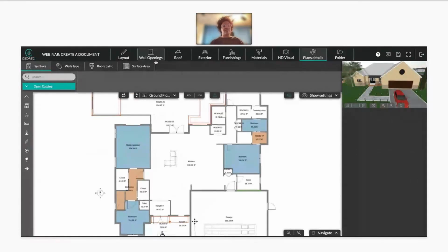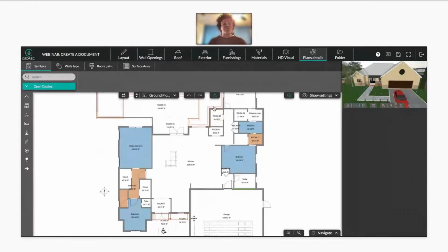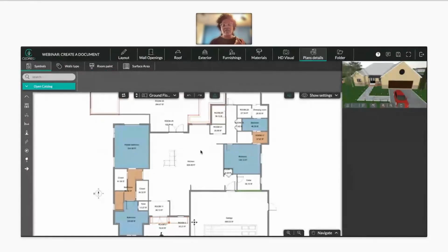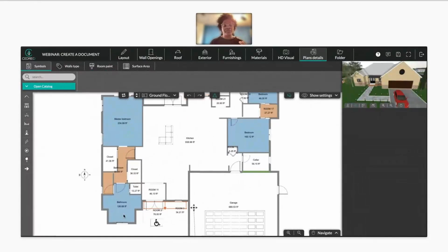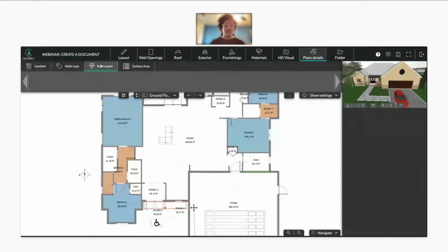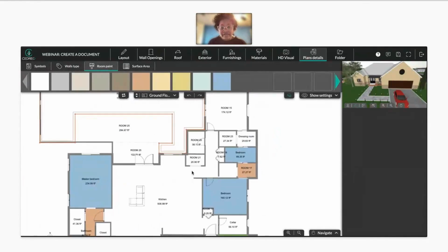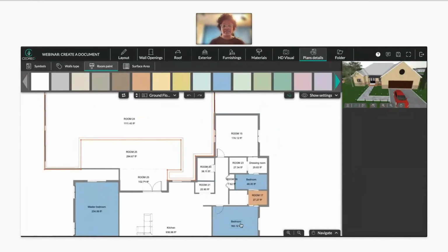All right. In your plan detail step, you can choose what these rooms are. So for example, here I want to show where blue is. This is where I'm indicating that everything in blue when I look at this plan is a bedroom. So I click on here. Do I have any bedrooms? Right here is a bedroom. Click on this blue, and I'm just going to drop it in right here.